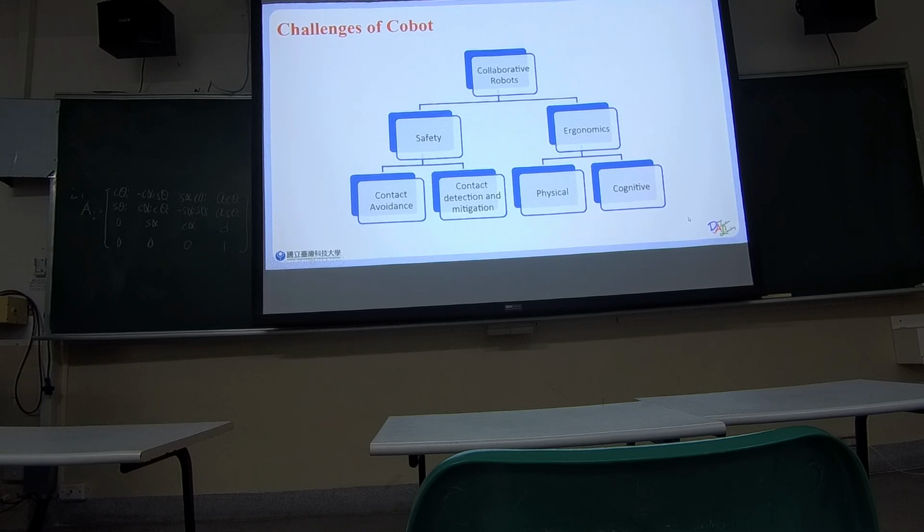In this regard, the robotic arms of cobots are typically equipped with force torque sensors, which can instantly capture collision signals when contact occurs and adjust the robot's behavior through intelligent control algorithms, reducing the energy released during contact with human operators. This design allows the robot to immediately alter its trajectory or reduce its speed upon unexpected collisions, significantly minimizing the risk of injury to the operator.